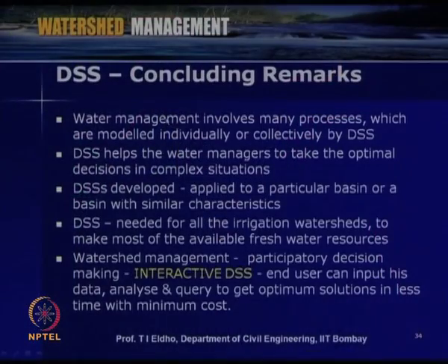So, to conclude today's lecture, some remarks: water management involves many processes which are modeled individually or collectively by decision support systems, and DSS helps water managers to take optimal decisions in complex situations, as we have already seen. DSS are developed and applied to a particular basin or a basin with similar characteristics. So, depending upon the problem, we have to specifically make the DSS depending upon the needs, and DSS are needed for all the irrigation watersheds to make the most of the available fresh water resources in an effective way.